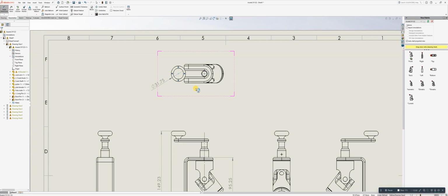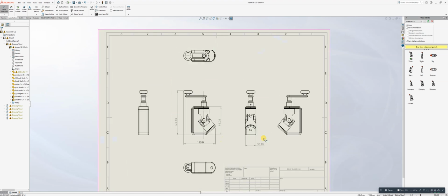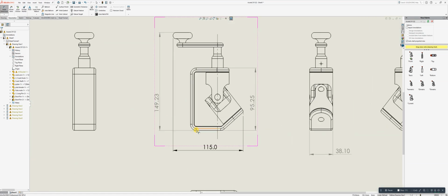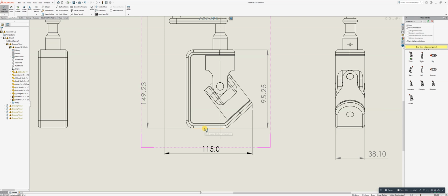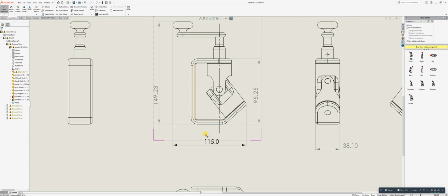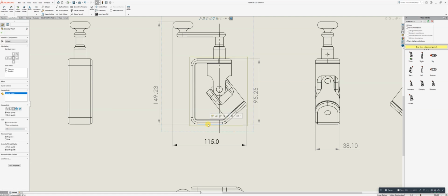I wanted to pick up on the centre. So stick with what we said before. I'll take that one out. It's generally just having a sort of mix-match of dimensions. Make sure that you have a datum point. Datum means your zero point where you're going to measure everything from. For example, at the moment, if I just come out there, that line there is my datum for that dimension and this dimension.